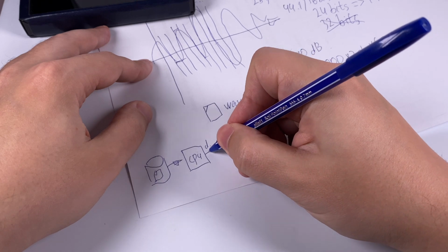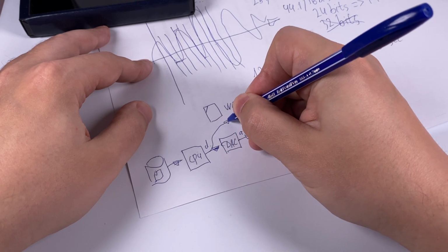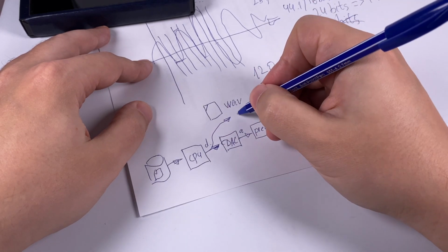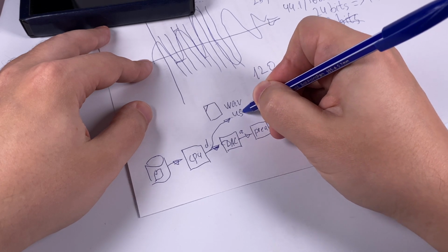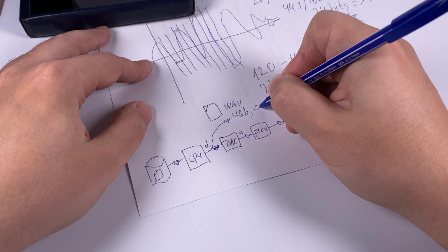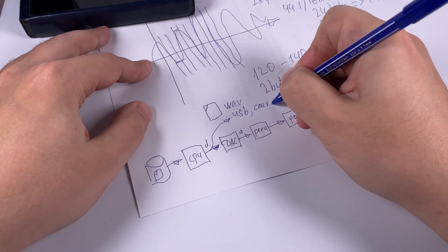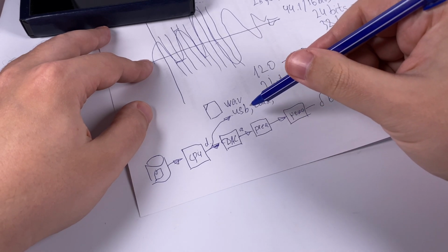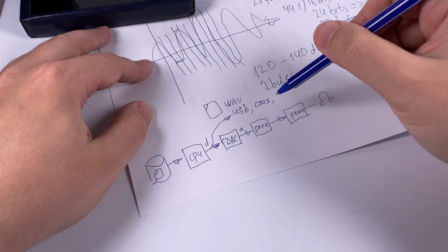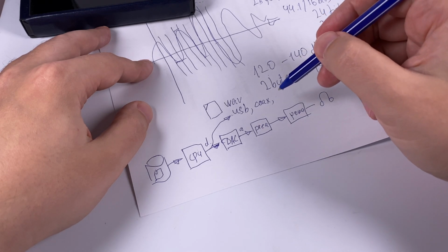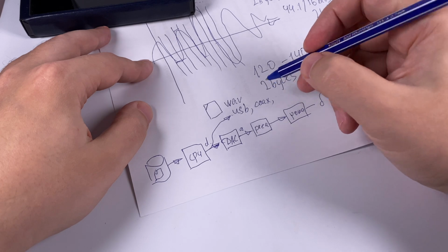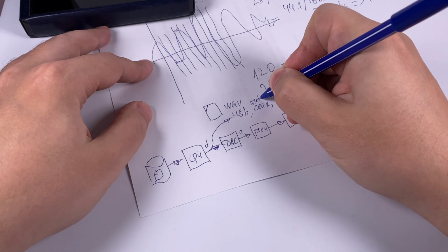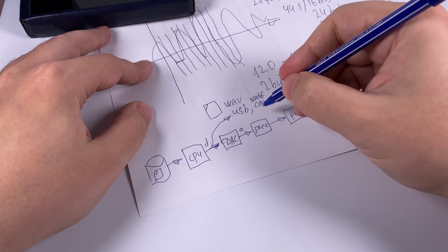First we can output the digital signal just after the CPU unpacking. We can output it to USB or coaxial. Sometimes other connectors are also used, but in players we often get USB and coaxial signal. And coaxial can be optical, and sorry, not coaxial, SPDIF. Yes, it's SPDIF, and SPDIF could be optical or coaxial.